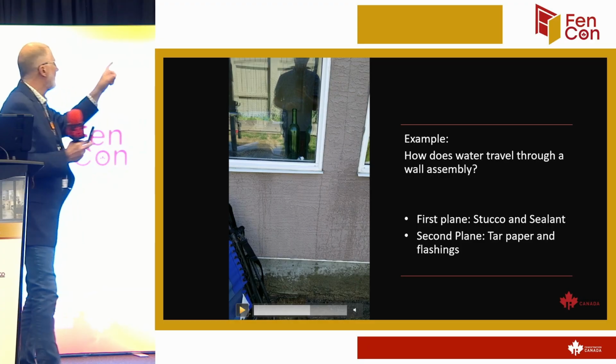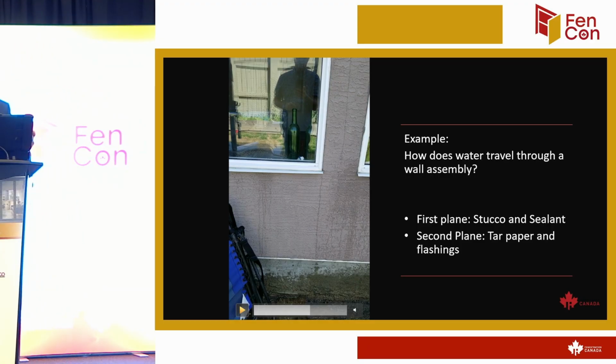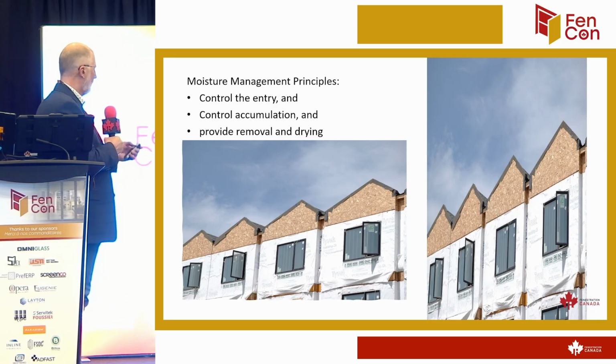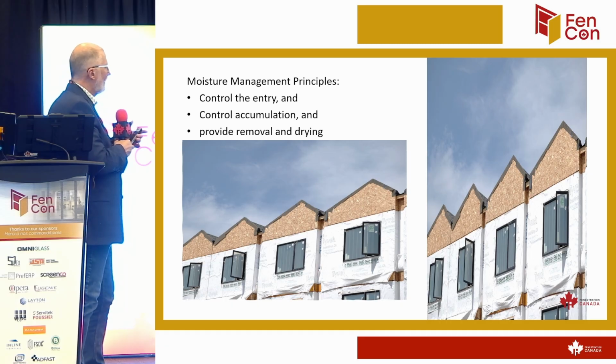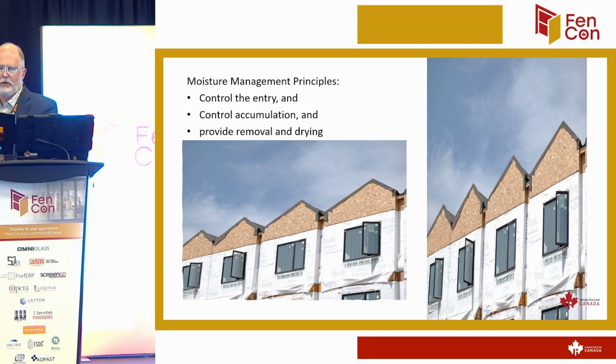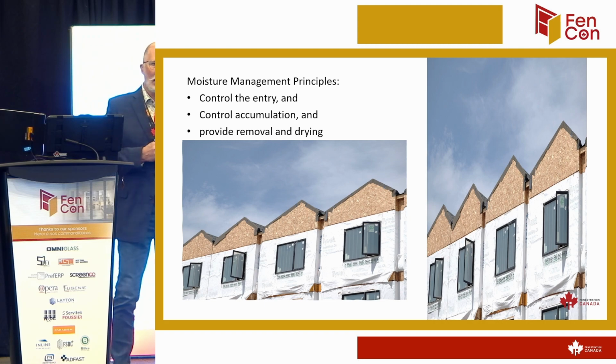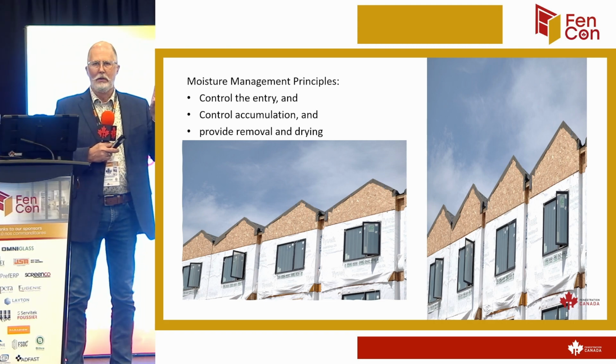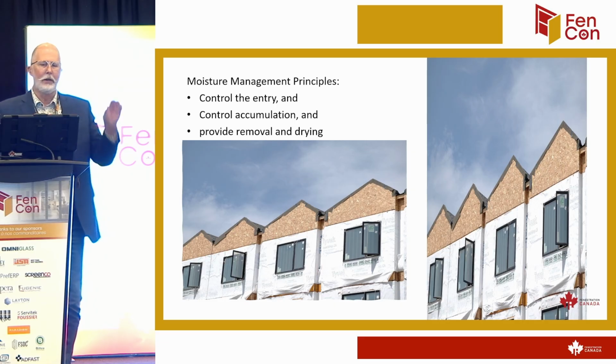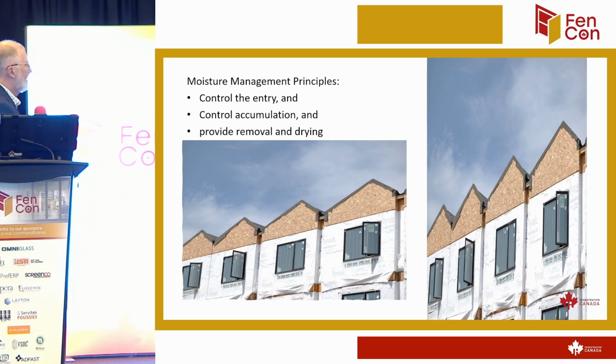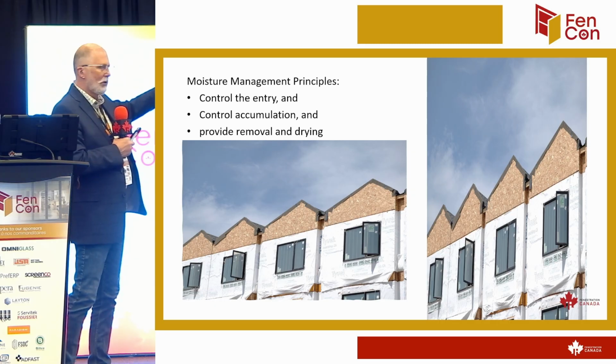So it's an example of water getting through there. First plane is working properly. There's some sealant missing, and that's what we were able to discover doing the test, but it was performing the way it was supposed to. It was getting rid of the water the way it was supposed to. The other thing we look at when we look at buildings is during construction, people don't always look at a building and properly detail it in a manner that the guy coming behind them is going to pick up on that, right? So here's a condo building. You can see that they've pre-papered the walls. They have not pre-papered the gable ends.